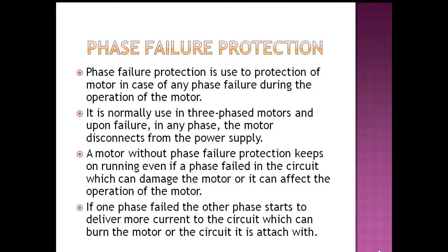A motor without phase failure protection keeps on running even if a phase fails in the circuit, which can damage the motor or affect the operation of the motor. If one phase fails, the other phase starts to deliver more current to the circuit, which can burn the motor or the circuit it is attached with.